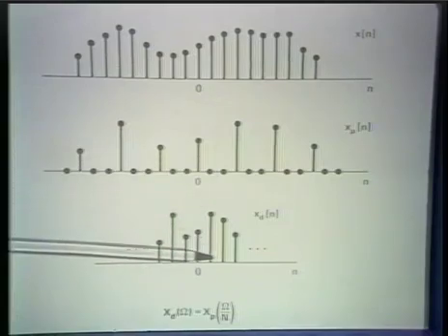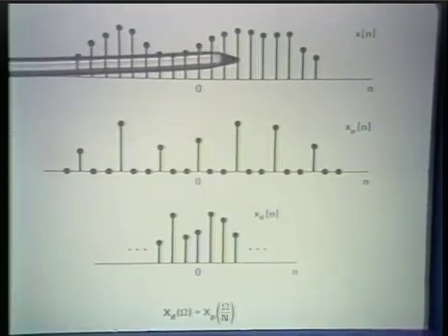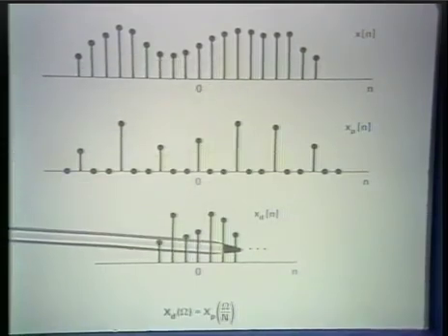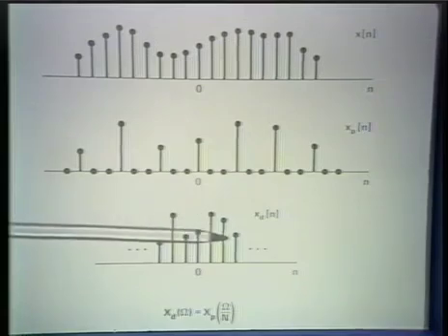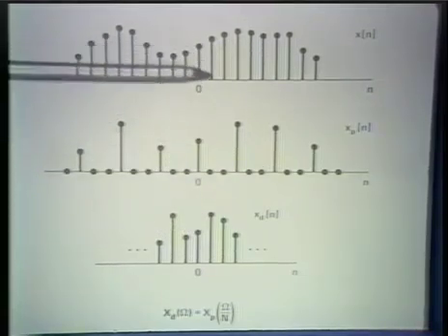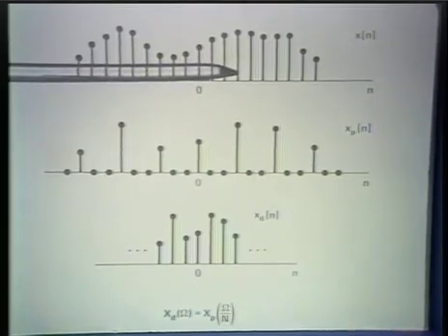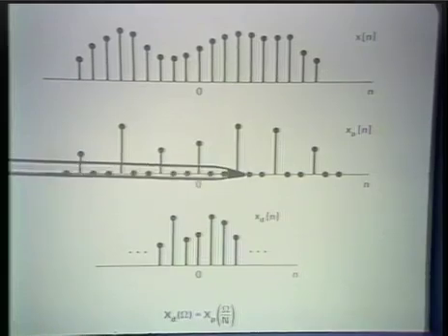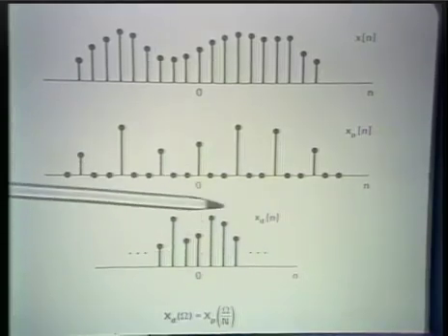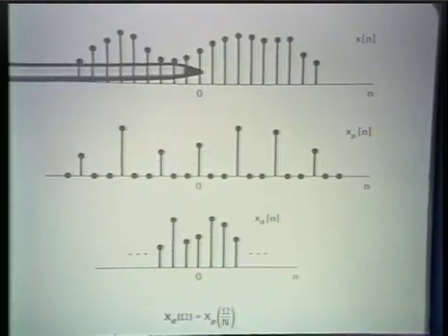Now, in talking about a decimated sequence, we could, of course, do that directly from this step down to here, although again in the analysis it will be somewhat more convenient to carry that out by thinking, at least analytically, in terms of a two-step process, one being a sampling process, then the other being the decimation. But basically, this is a decimated version of that.